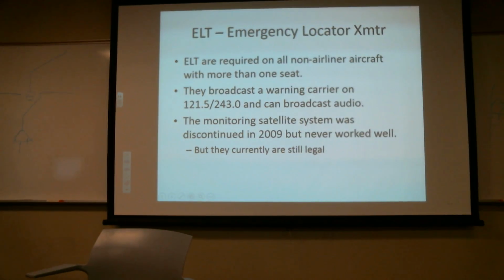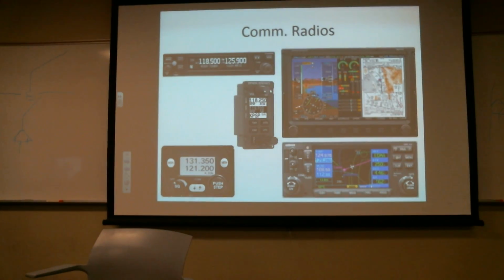What's the output of a handheld radio typically? A handheld? Typically no more than about 5 watts. And they say max output is 5 watts. What they're really saying is if you're at that one frequency that the antenna is really well tuned for, and nothing else is going on, and your battery is really well charged, you might hit 5 watts. But pretty much anywhere else, you're not going to hit 5 watts, because those little rubber biscuit antennas aren't that great.